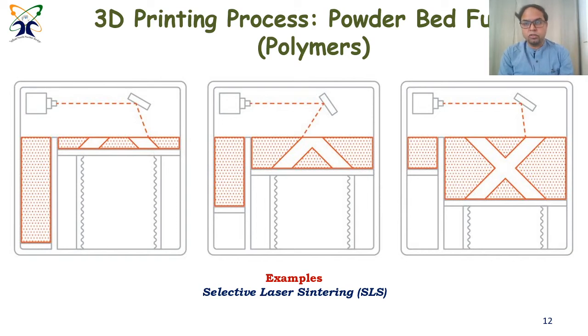So instead, you make a powder of it, and in the powder bed, you use a laser to selectively heat the interaction region, and it locally melts and fuses it. So it's powder which is converted into a molten thing using the laser and then fused. That's how you get 3D printed metal objects, or objects which are made up of alloys.